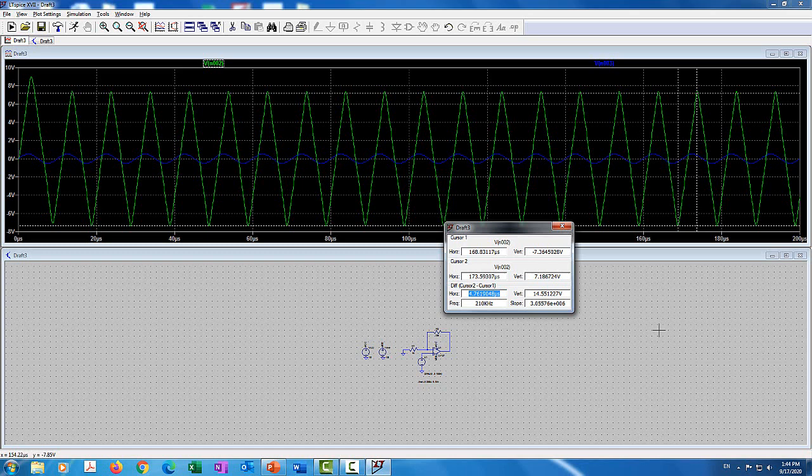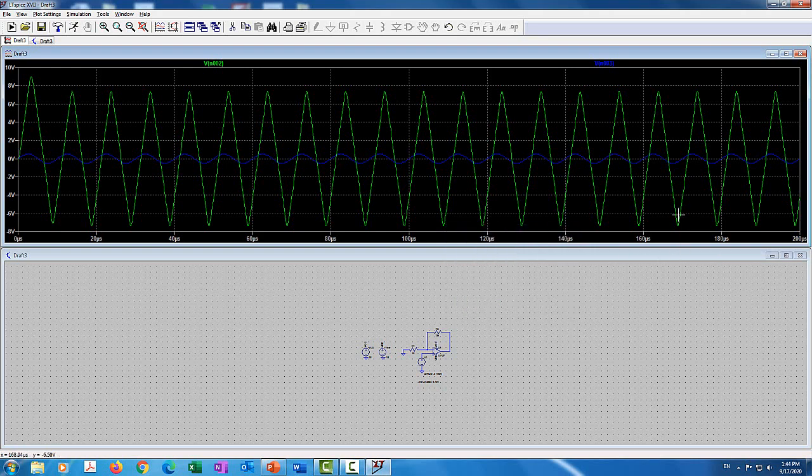So if the sine wave is changing faster than that, it's going to be a straight line, because all the op-amp can handle is this maximum dV out/dt. You end up with a straight line. It is actually distorted. I can get rid of this distortion very easily at this frequency. All I have to do is minimize the delta V out. So if I make delta V out very small, then I might not exceed the slew rate. And let me show you how we can do that.